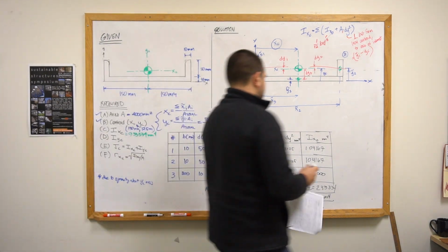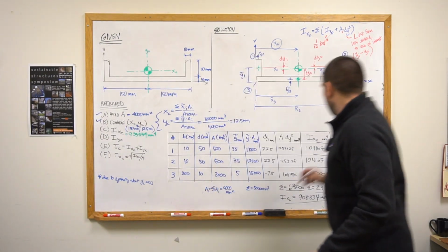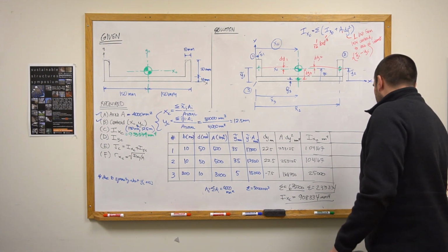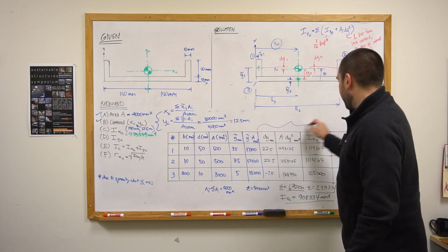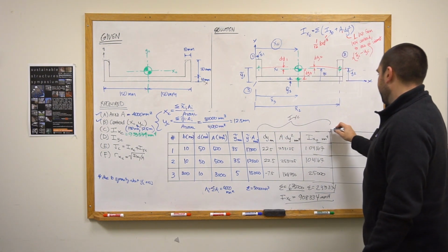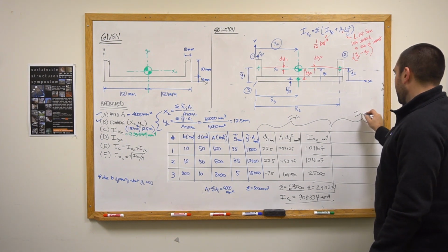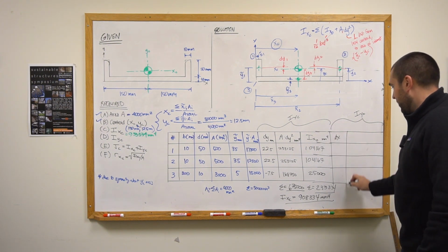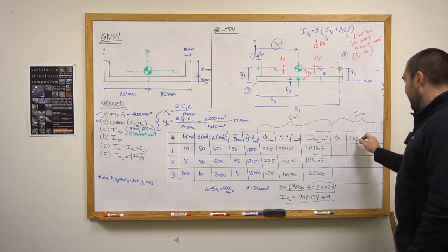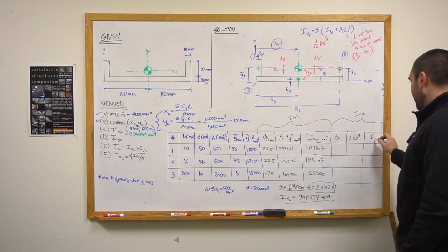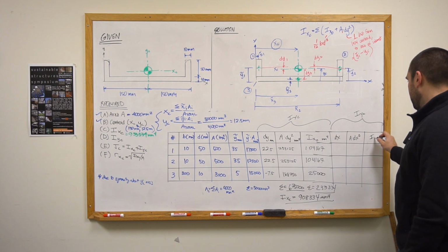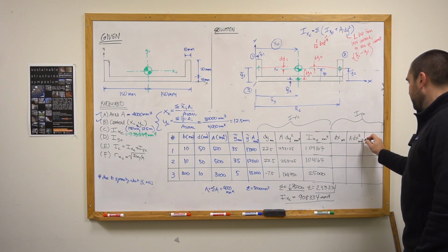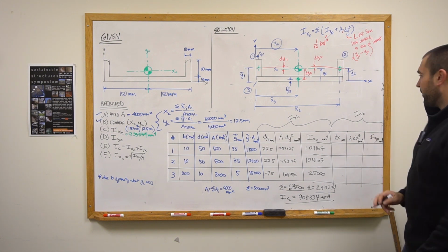The same exact process is followed to get the moment of inertia about the y sub c axis as well. Whereas these terms right here are for IXC, the next three terms here need to be for IYC. And that's going to be dx, a times dx squared, and Iy naught. Millimeters, millimeters to the fourth, and millimeters to the fourth.